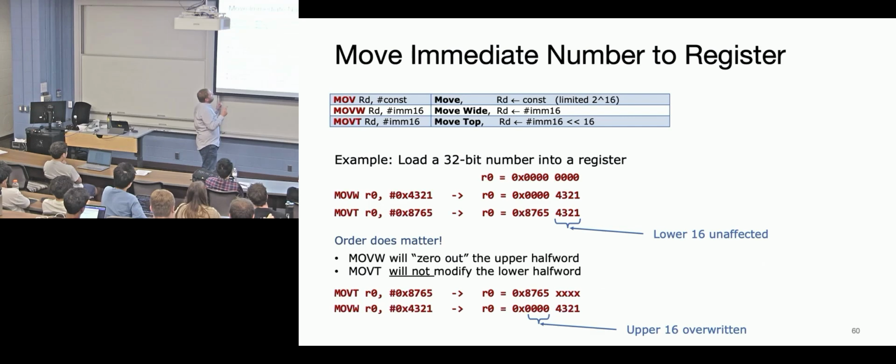Move W. Well, okay. I don't think I can put a 16-bit number in a 16-bit instruction. I'm just thinking out loud, and you're not wrong, because this is the intricacies of how the assembler works. If you try to write assembly that moves a number larger than 16 bits, the assembler will choose to use a 32-bit encoding for that, because there are multiple ways, as we saw from the move S before, depending on what numbers you put in there, that give you different encodings.